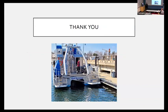So there's a graduate student named Casey O'Hearn who did a thesis where he used drones to collect photogrammetry and LiDAR data sets as it flew grid search patterns over the top of a vessel. And then he was able to derive the horizontal offset estimates from those data sets from the drone. And he was able to constrain the horizontal uncertainty to within centimeters using some of those methods. And there's also a paper on that published as well. Yeah, his thesis is published.